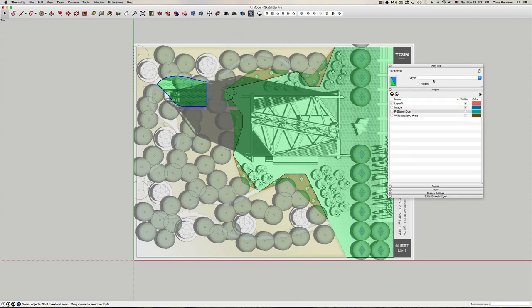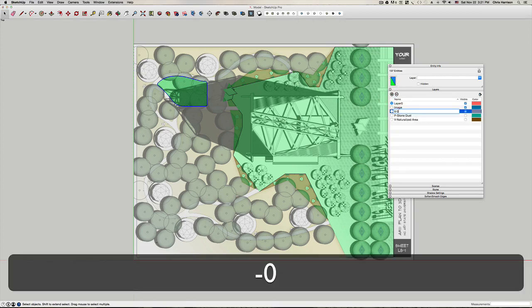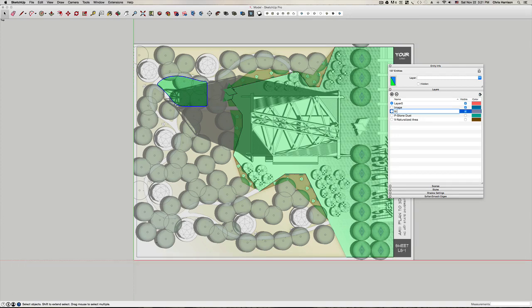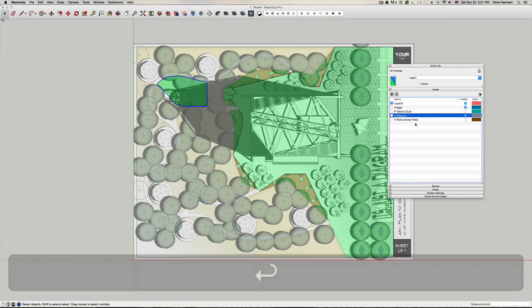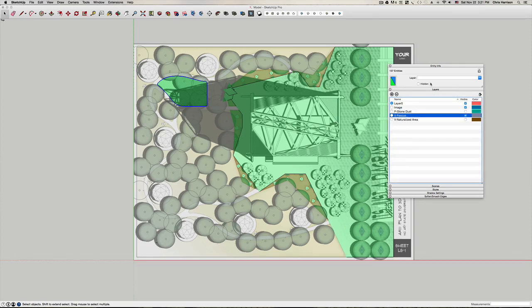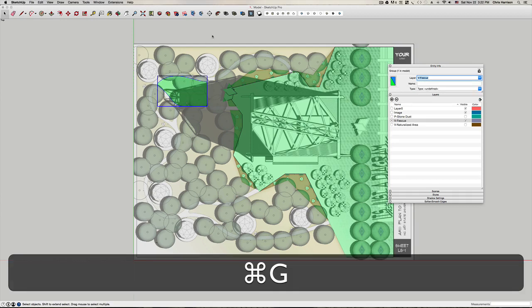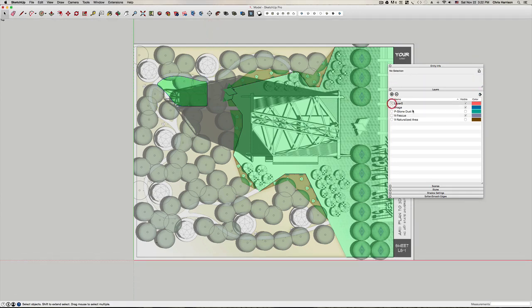This is just going to be a random lawn area. Create a plus sign. V for vegetation, and I'm going to call it lawn or fescue area. And put myself on that. Make sure that this is on that, and make that into a group. Okay. I should be able to turn that off now. Great.